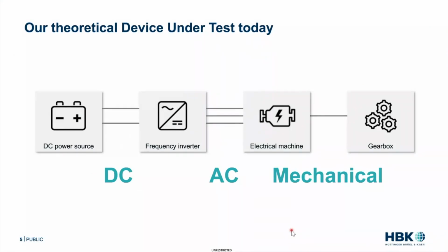So in our powertrain today, we all know this, but we have DC power measurements, AC power measurements, and mechanical power measurements. DC coming from that battery or power supply. AC is our 3-phase, 6-phase, pick your favorite number of phases, coming out of the inverter. And these are high frequency signals because that inverter is turning on and off at tens of kilohertz. We're creating sine waves at hundreds of hertz. Those are going into an electric motor, turning those electric currents, that high frequency AC voltage and current, into rotational energy, and that's going into a gearbox. So we got a lot of interesting stuff.